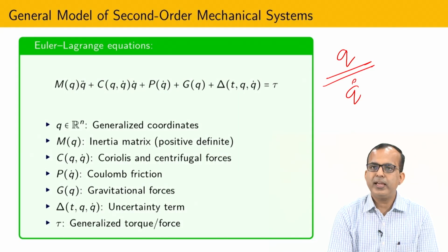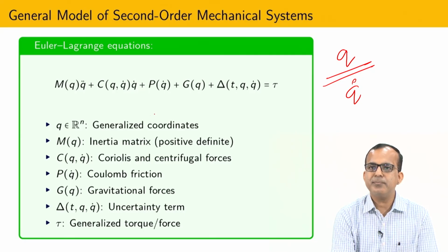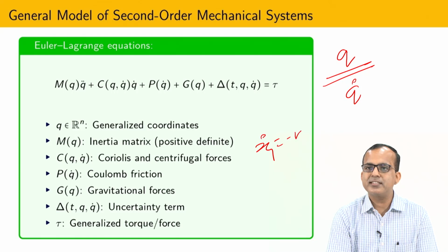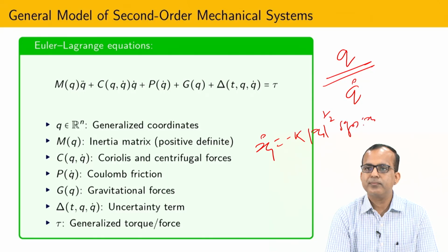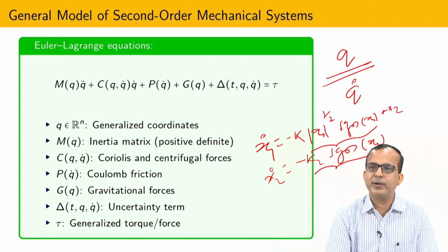Now, another way I can design some kind of finite time observer. I have a second order mechanical system, and we also know the super twisting algorithm. What is the structure of the super twisting algorithm? You can see that the structure is second order, but everywhere in this structure the second term contains just the information of x1. So, here I have information of x1, and here also I have information of x1.